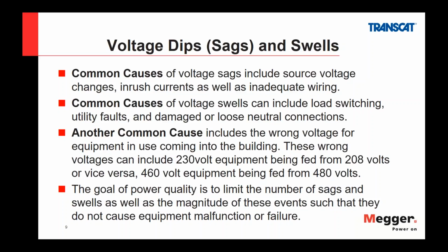As the load turns on, the impedance decreases, which increases the current, which can cause a drop in the voltage. As the load turns off, the impedance increases, which can lead to a swell in the voltage.